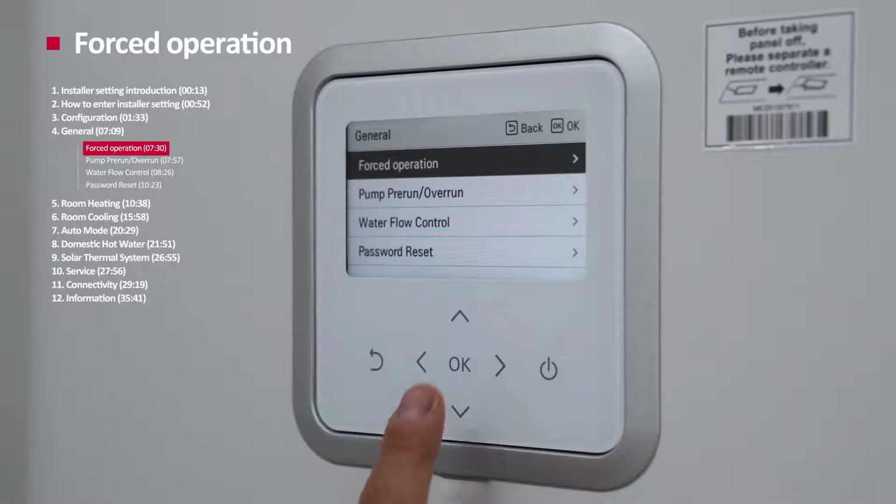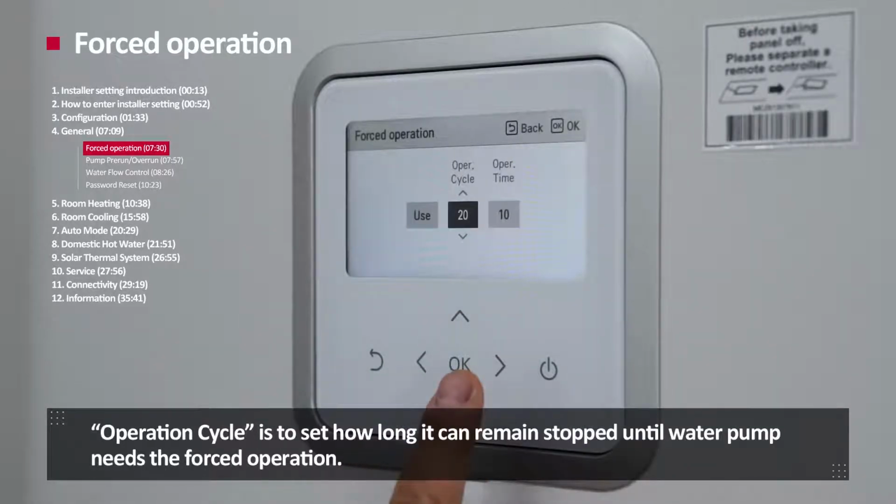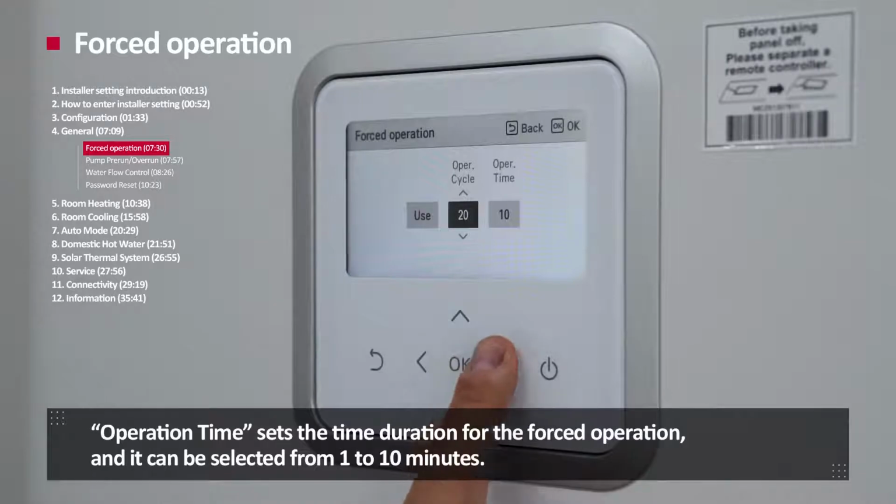Forced operation. When the product is not used for a long time, the pump is forced to operate to prevent pump failure and freezing of the plate heat exchanger. Operation cycle sets how long the pump can remain stopped until the water pump needs the forced operation. Operation time sets the time duration for the forced operation, and it can be selected from 1 to 10 minutes.